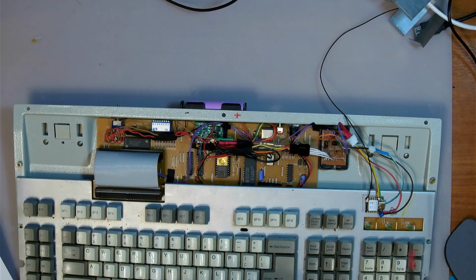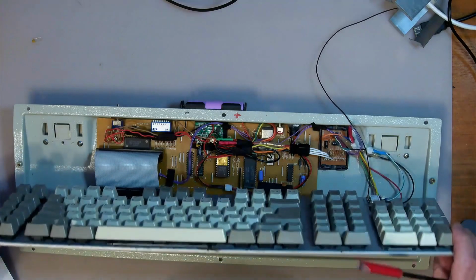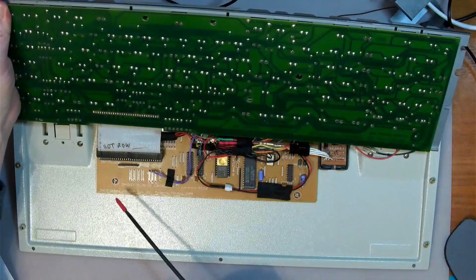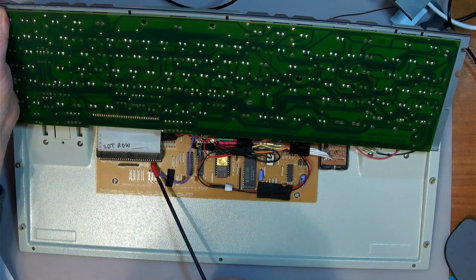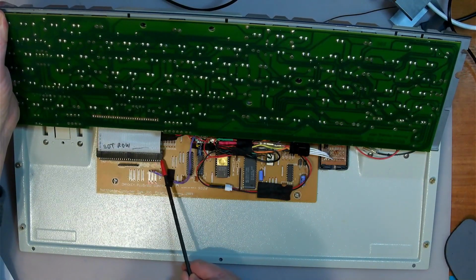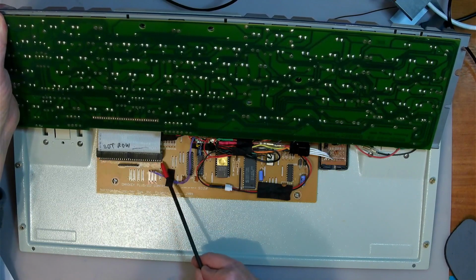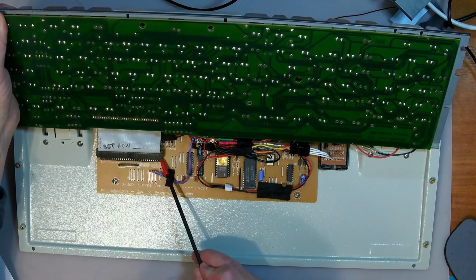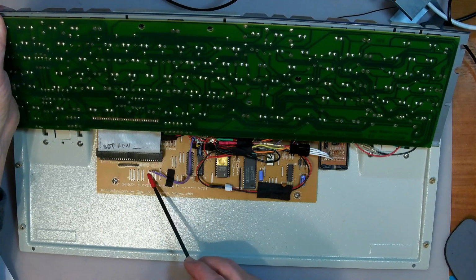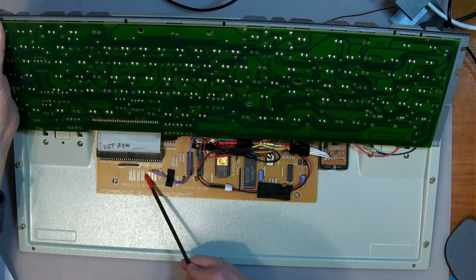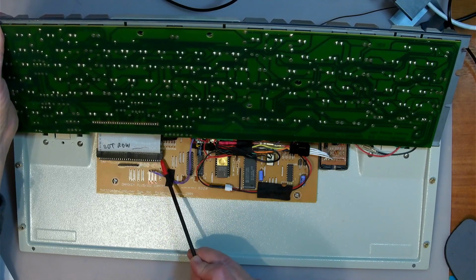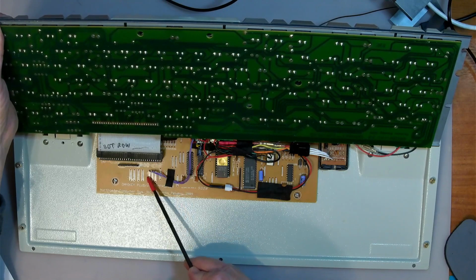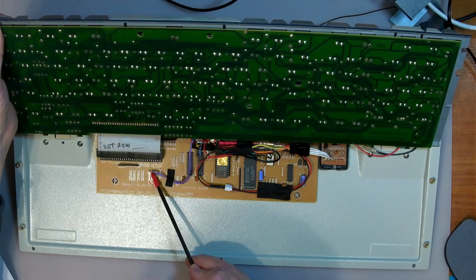I have also actually, if we look at this over here, finally you'll find that those three pins over here are connected to those three LEDs. This is VCC. There's actually no ground on this connector, interestingly, and when these signals are pulled low, the LEDs come on, because after all it's got VCC and a resistor to the LED, so you pull them low and then they will glow.